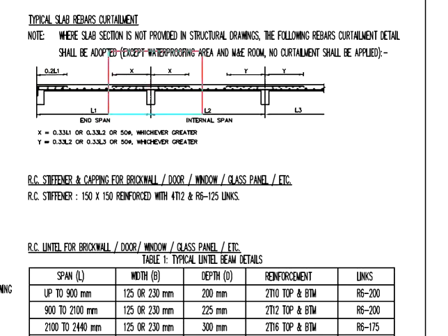As for the intermediate span, we are going to look into three possible components. First, it will be 1/3 of the span itself. Second, it will be at least 1/3 of the adjacent span. And then third, it will be at least 50 times the bar diameter.